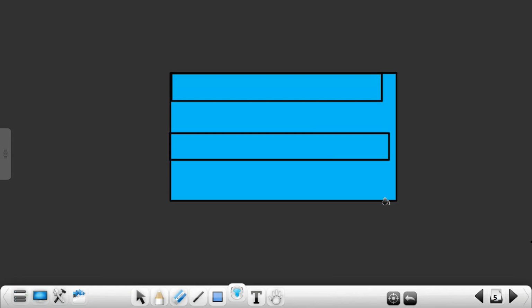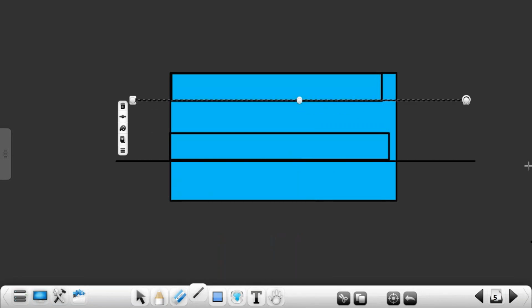After that, the foundry starts etching, which means cutting, removing the metal wherever it's not required. Etching is a chemically driven process. You treat it with sulfuric acid or highly concentrated acid, and the metal melts away.